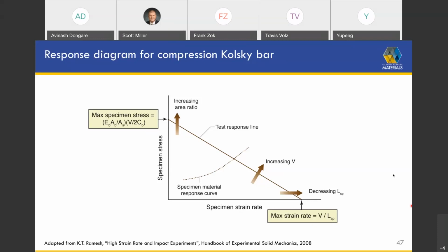Okay. So measuring the stresses, what you're essentially doing is computing the forces. And you get those forces, as you suggested, using the strain gauge. That gives you the strain in the bar. You know the area of the bar, and you know the Young's modulus of the bar. So that gives you directly a measure of the force being transmitted through the bar.